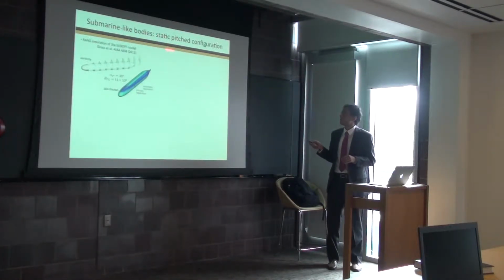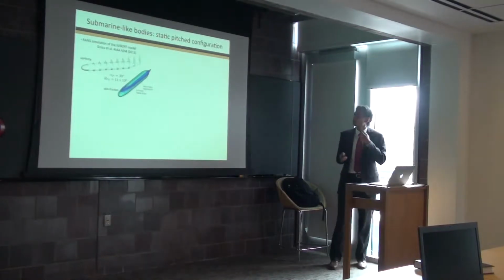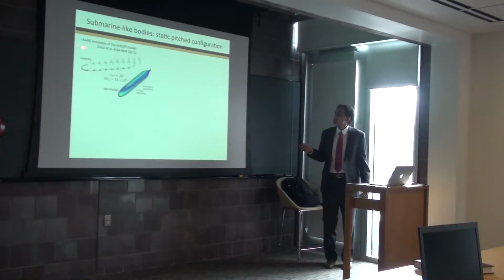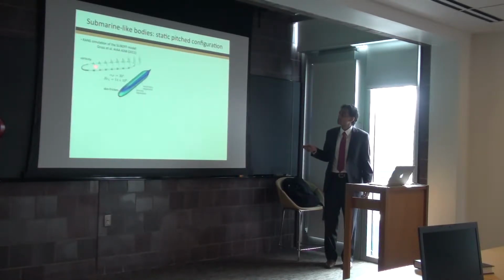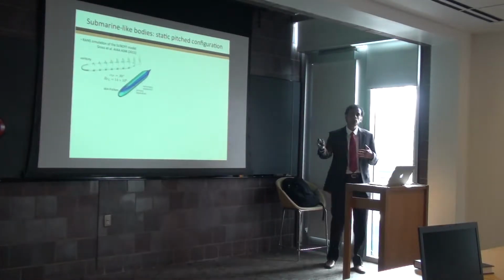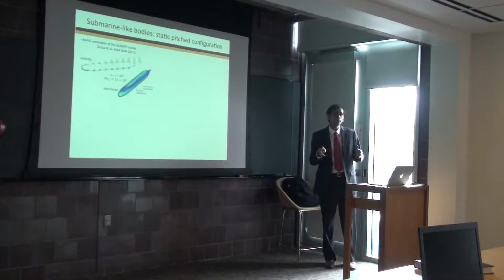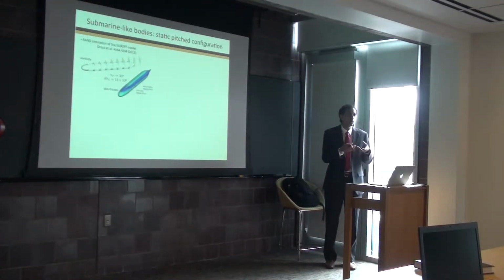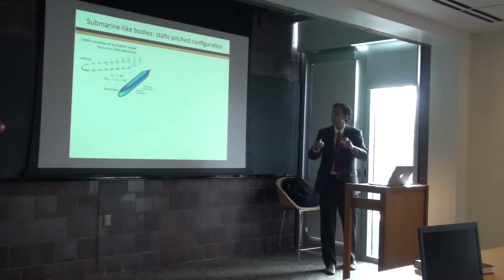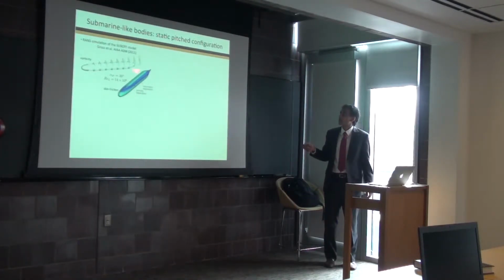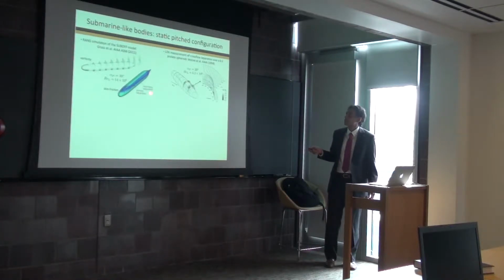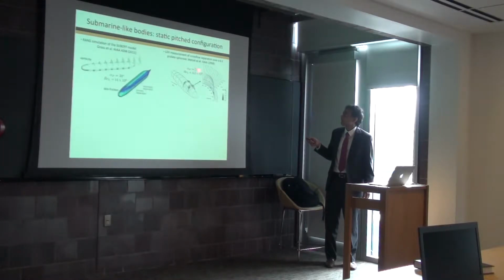We focus on the static pitched configuration in this study, so a few words about that. This is a simulation by Gross et al. So here you see vorticity and skin friction contours shown. His main purpose here in this study was to look at the Reynolds number effect, and he found that there was a qualitative change in the topology going from a closed separation bubble type separation to what's known as an open separation that occurs. He did not trip the flow, and therefore he did not see secondary vortices, which are characteristic of this flow at high angles of incidence.